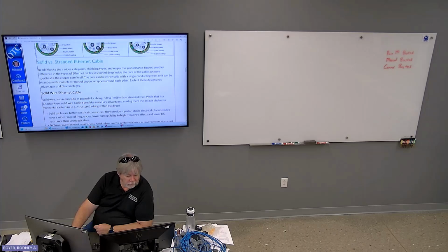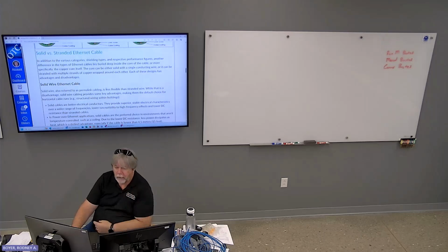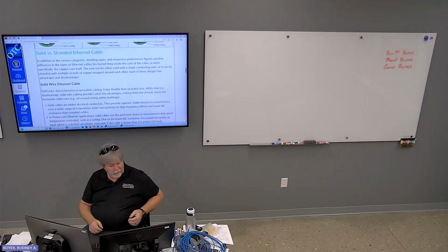So anyway, solid is used for permanent cable runs. And then the stranded is for patch cables, where you're constantly flexing it.